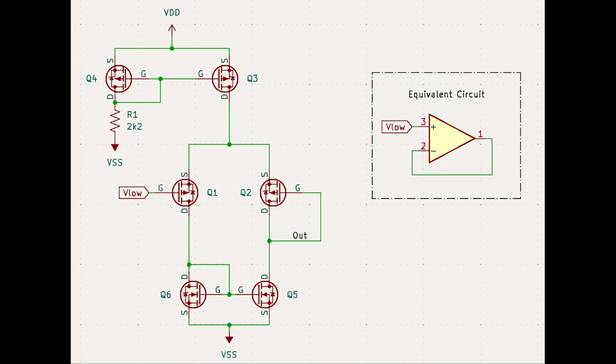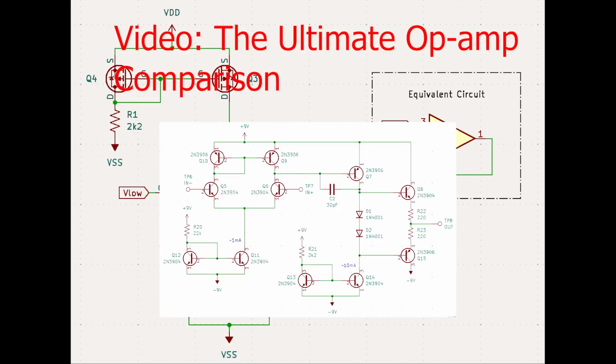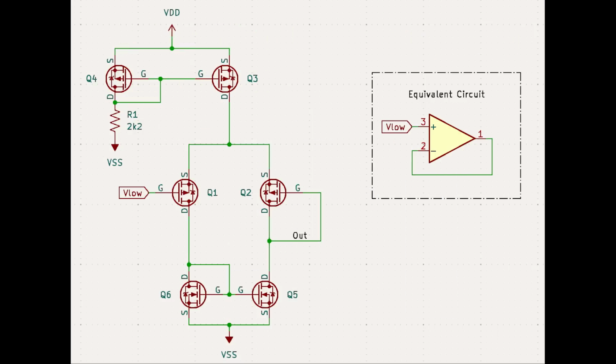It's a lot like the op-amp that I've shown you in a previous video. I'd recommend watching that if you don't know what I mean when I say differential pair. I've gone ahead and changed this design to use MOSFETs because they have much higher input impedance compared to BJTs, which is the thing that will allow us to eliminate the string buffers. Anyways, as you should know from the op-amp video, when we wire the inverting input to the output, we buffer the output. In other words, the voltage on the non-inverting input is buffered onto the output.